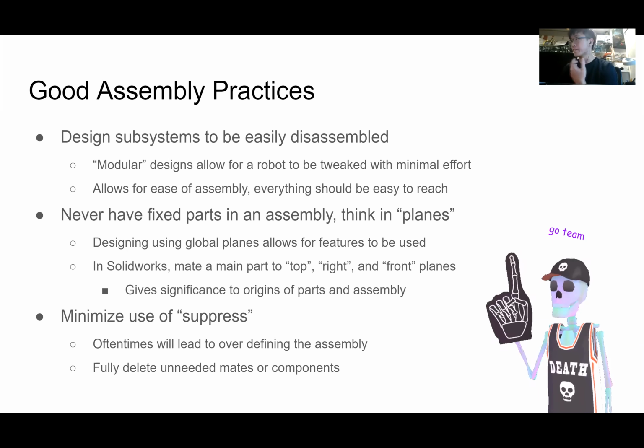Also, when I say think in planes, also think about when you're designing a part, whether you should sketch on the front, top, or right plane, just so that you're consistent when designing an assembly.